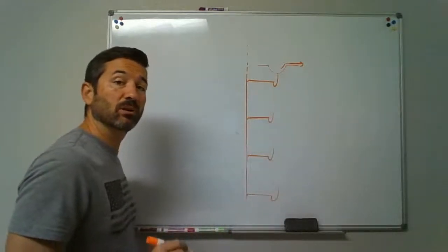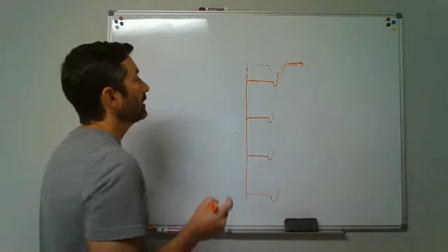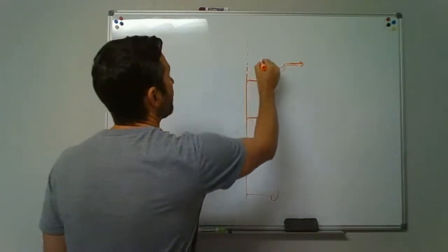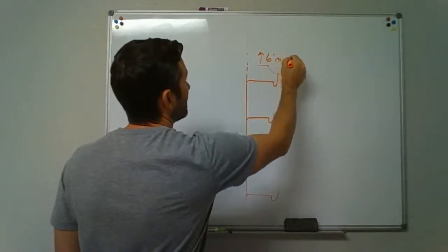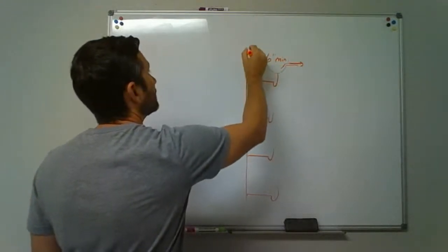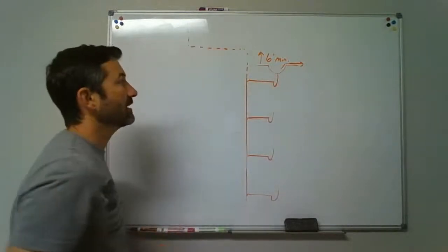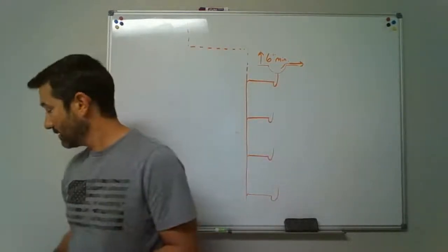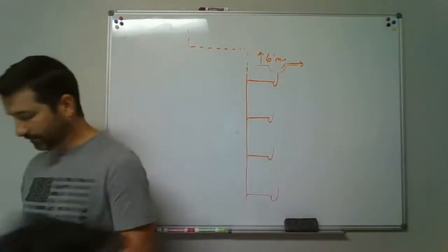If you see it abbreviated, you might see FLR, flood level rim. Now, if we're going to put an offset, you've got to go up above that higher, 6 inches minimum, before you can offset that if you needed to lay it down. Okay.